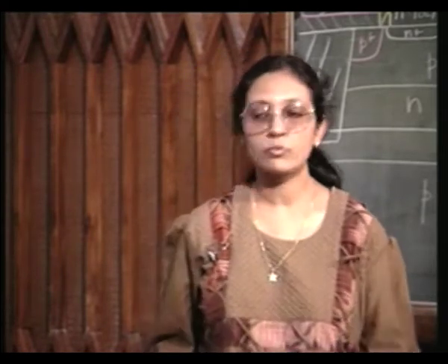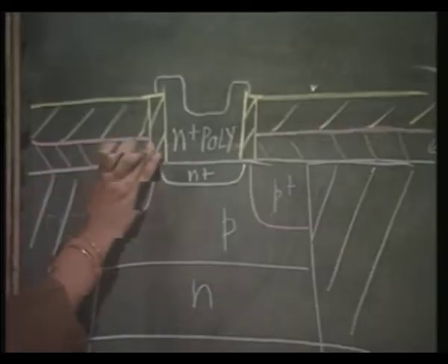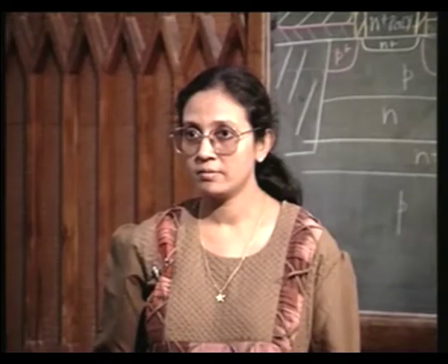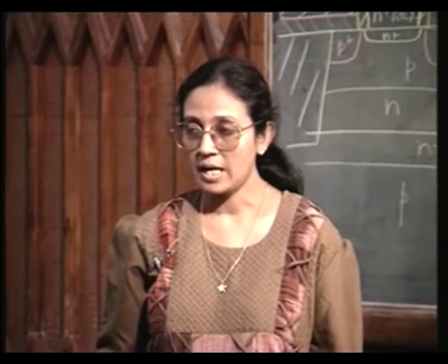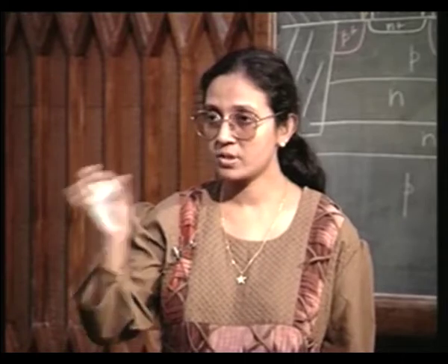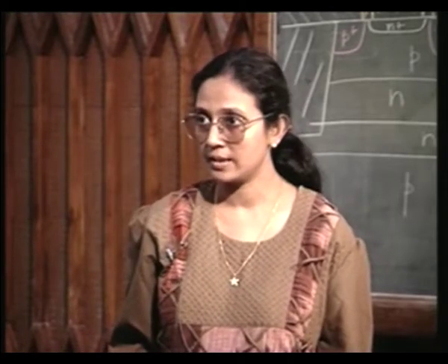Okay. Here you have to control the CVD SiO2 thickness. There you are simply controlling the CVD poly thickness, which can be made very thin. And then when you oxidize it, it expands and gives you adequate spacer layer thickness.